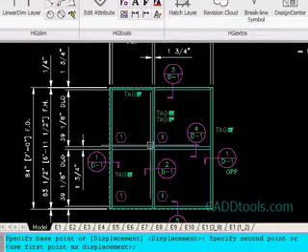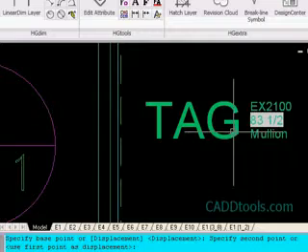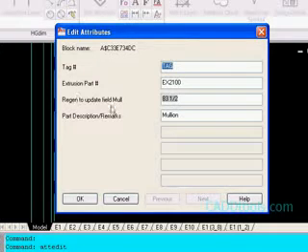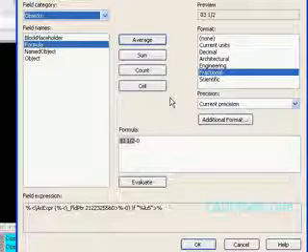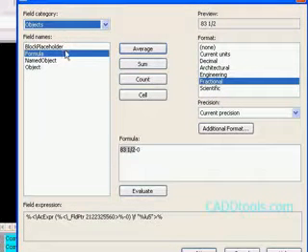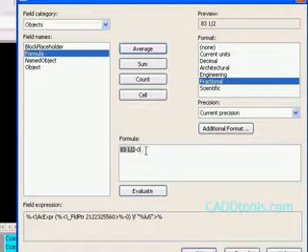Okay, a note about the associated field. We'll go into the attribute editor. You can see that this one is associated with that line. You double click in that field, and you can associate. Originally I associated that with a name object, but I wanted to be able to use formulas, because in some cases, like with curtain wall, like a pressure plate, you'll want to do daylight minus 1/4 of an inch.